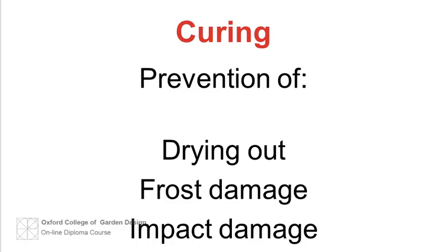Essentially, the curing of newly poured concrete is to ensure that the cement has sufficient water to complete its chemical hydration process and to avoid damage by frost before the concrete has sufficient strength to resist the ice expansion. Concrete does not set by drying out. Concrete can even set under water, provided the water has not washed out the cement from the mix. Proper curing of concrete will improve both its durability and its strength.